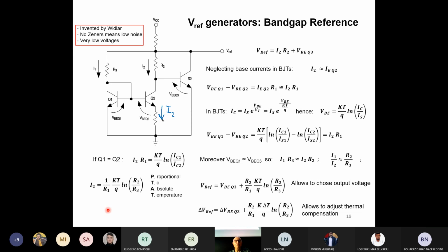This term alone can be used for making a very nice thermometer, the one for measuring temperature, not the old mercury one. So when you buy a chip which is used for measuring the temperature, probably it will work on this principle here. If we have time, I will show you a nice simple circuit which is called the LM35.